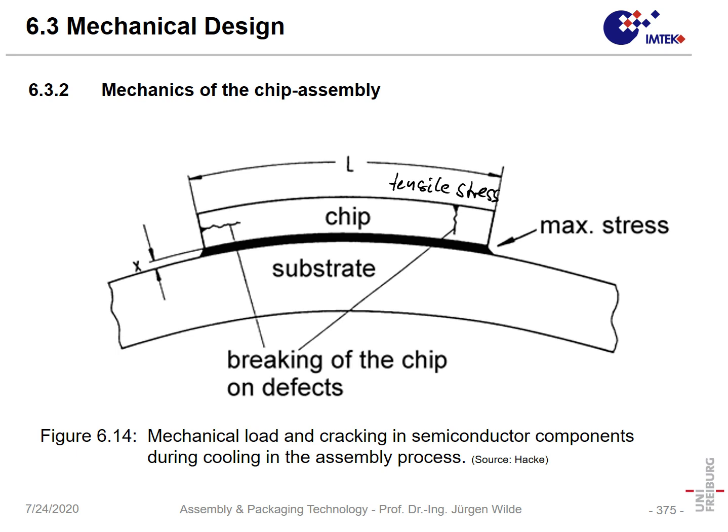No, you will close it. But by tension you will open a crack, and the crack will tend to propagate. So tensile is worse. On the other hand, we can also have cracks from the side of the chip, and that is typically a result of shear stresses in the chip.